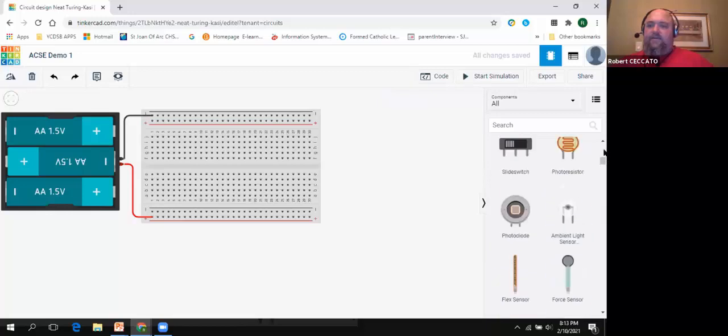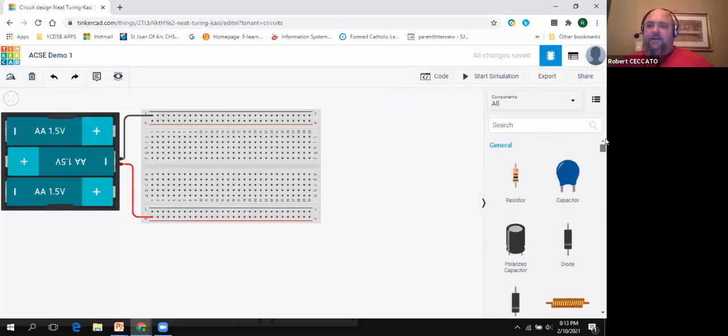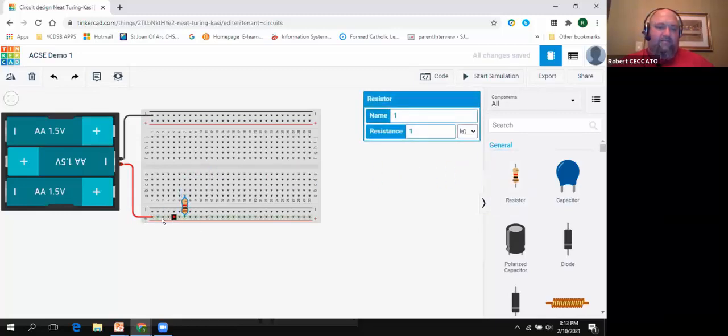And we keep finding one. And then we get up to the top here, and we're like, there's a resistor. So I'll pull my resistor over. I'm going to put it into the positive rail, right? Because electricity is going to come out of here through the resistor, and now it's going to light up or put power on this column.